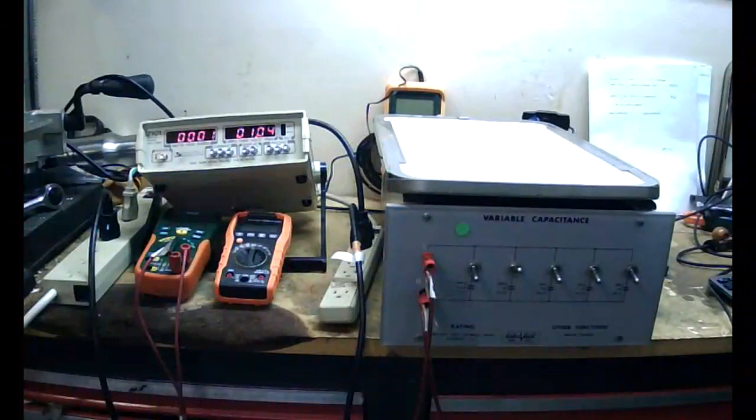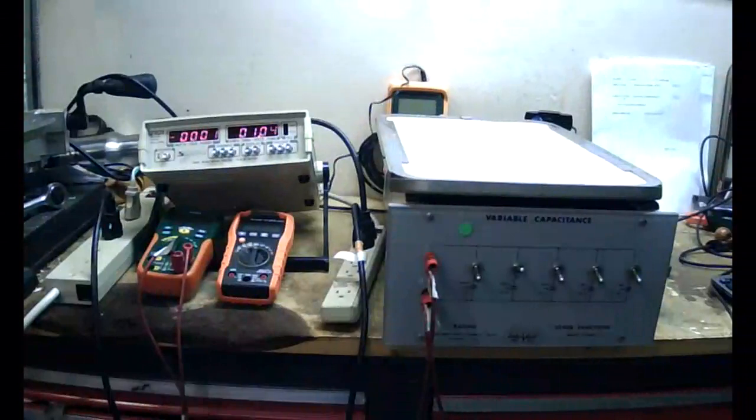In practical terms, utilities will charge commercial and industrial customers for low power factor, but low power factor usually starts at 0.9 and below. So we've gotten it to 0.96. We are fine as far as the utility is concerned. We just need to keep it above 0.9. Doesn't really matter if it's leading or lagging. We could figure it out, but we don't need to.